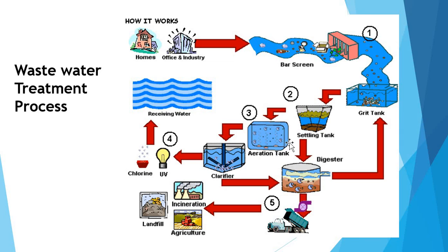The secondary treatment is an activated sludge process in which microorganisms help in changing the solids into three phases: the solid phase, liquid phase, and gaseous phase. The gas will escape to the atmosphere, the liquid is collected in the clarifier, and the solids are collected in the sludge digester.